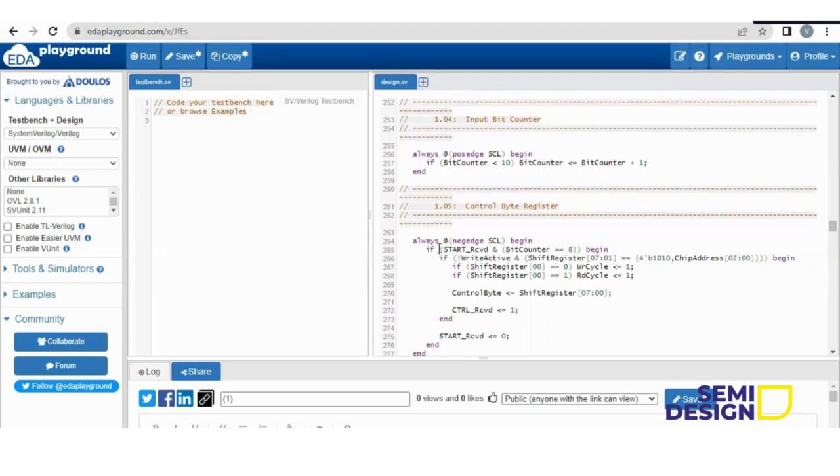So when all these conditions are satisfied, what they are doing is bits 7 down to 1. This chip address value, they are storing here. And here they have taken one fixed value. See, this is a total 7-bit value. My chip address is 3-bit, so for the rest 4 bits they have taken this constant value. Okay. So now shift register. You understood this, basically what is happening in this shift register: they are storing the chip address value. You understood this part?